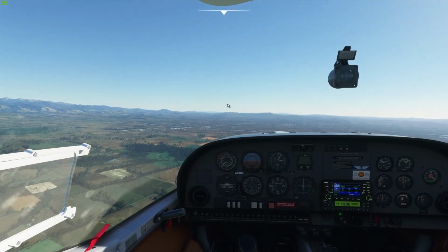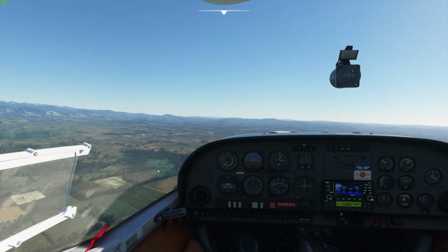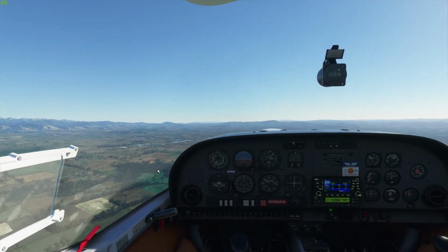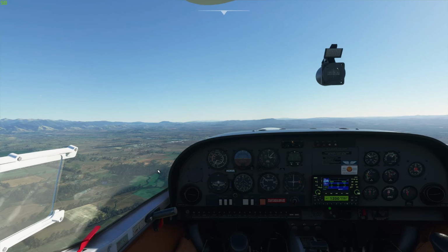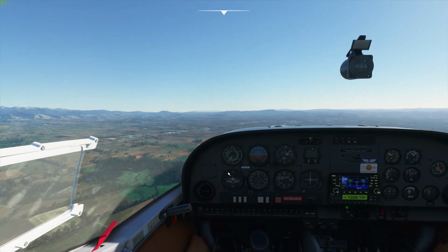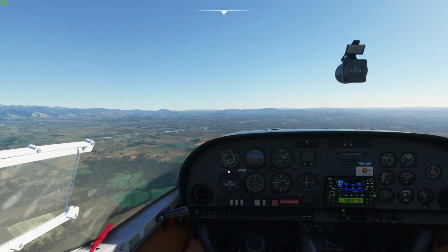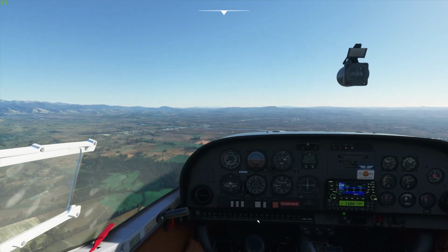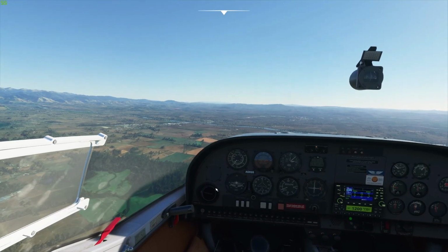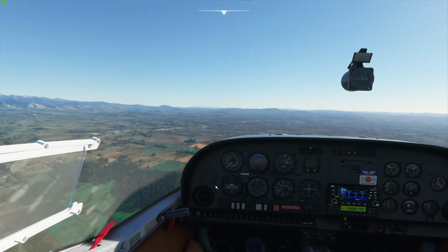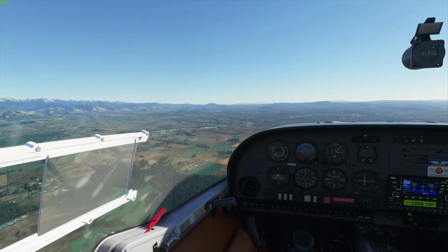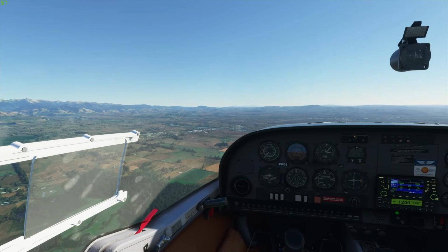That means that the rate that the nose is moving up and down has reduced from when we did that first input. And it's almost back to its original speed. It's 90. So that's what we'd call a positively statically stable aircraft, because it's pretty much returning to the original trim configuration that it was in, which is good news.